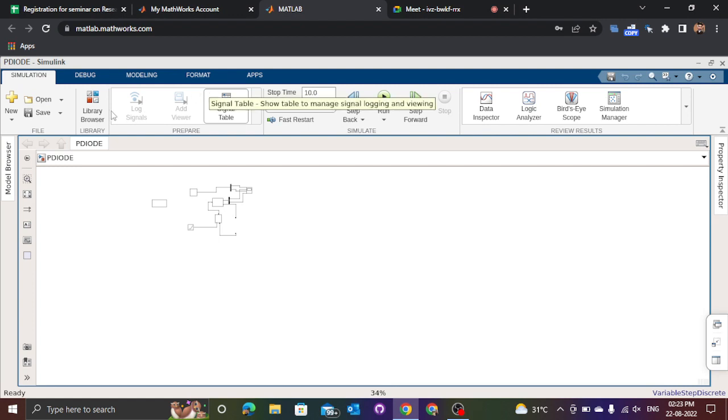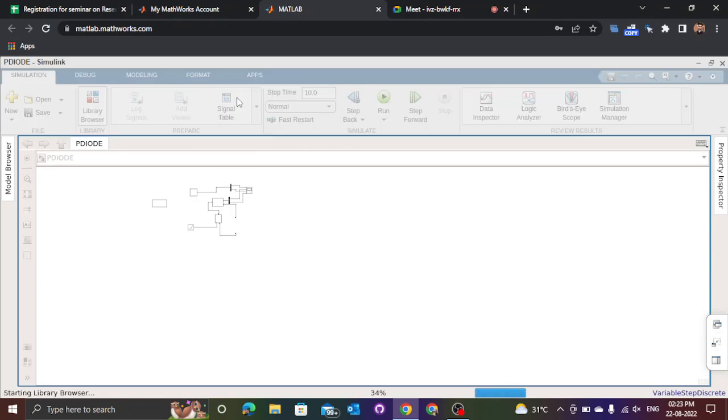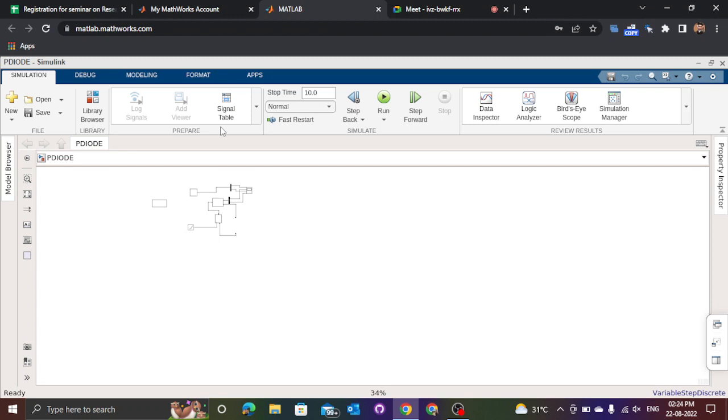Okay. Whenever you type Power GUI and click Enter, you will find a block written as continuous, and it is for Power GUI. Okay, then double click on it. Then you find a simulation type in the block. Are you able to do this?